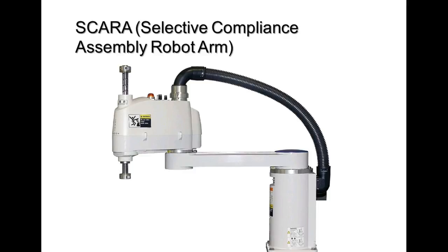We've got 1 rotary, we've got 2, so this would be a 2R. Okay, 3R, because this guy right here can rotate, but it also can go down. So it'd be a linear axis that can rotate, right? You understand? So this would be a 1, 2, 3, 3R, P.